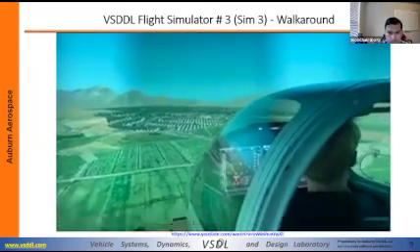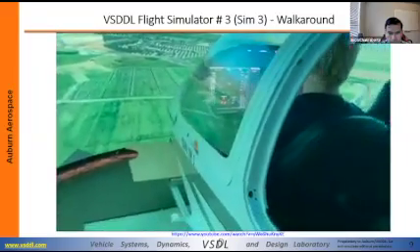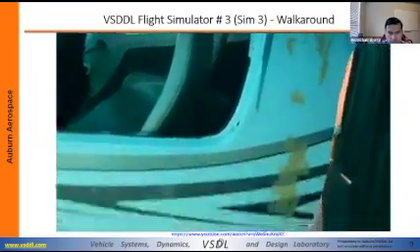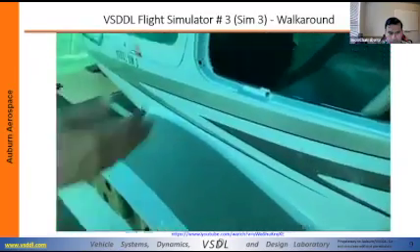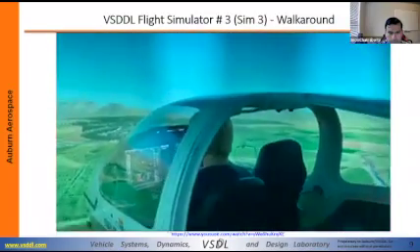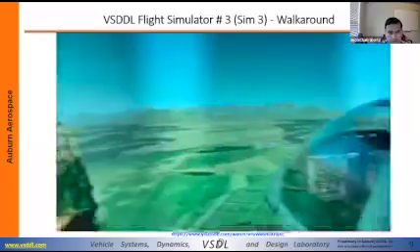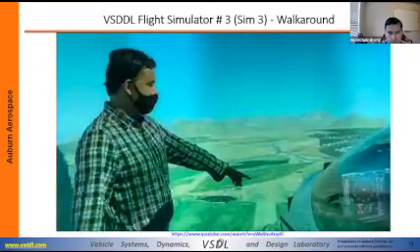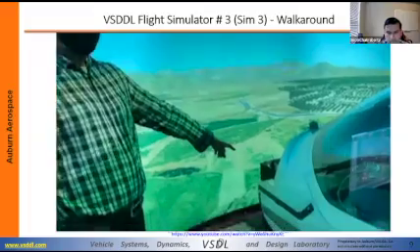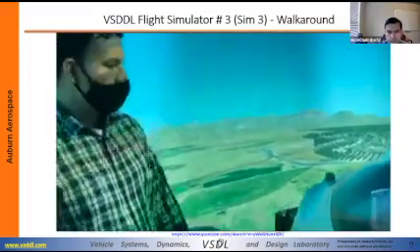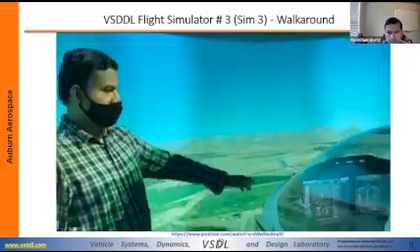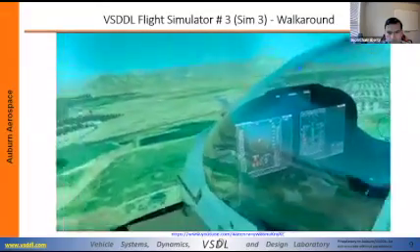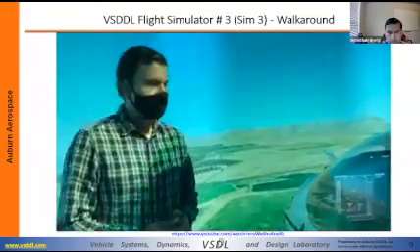SIM3 uses a cockpit that is based on a Diamond DA40, so this was a non-airworthy Diamond DA40 airframe that was donated to us. So the cockpit, the cabin section, we basically repurposed that for this simulator. There's one more computer over here. This is the displays and controls computer. This is responsible for driving the cockpit displays, for capturing inceptor inputs from inside the cockpit, and also generates audio.